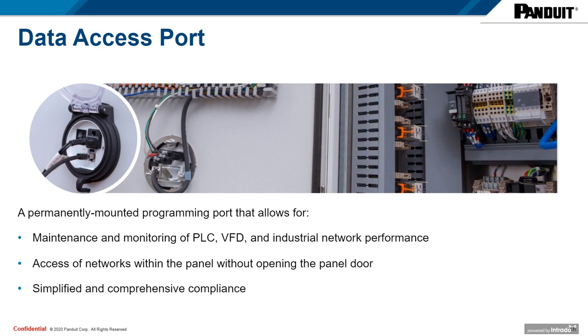These data access ports were designed to be completely modular, allowing for ultimate design flexibility, field upgradability, and adaptable inventory. Additionally, power can be made available on the panel door to keep a computer or laptop charged during the maintenance or updates. Security provisions such as a quarter-turn lock and padlock loop prohibit unintentional or unauthorized use of the programming port or power. The Panduit data access ports are also UL listed, which allows for simplified and comprehensive compliance.